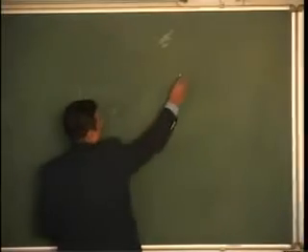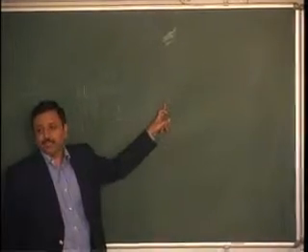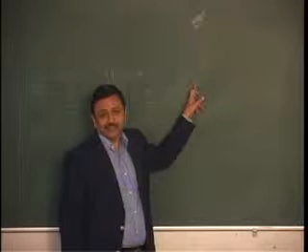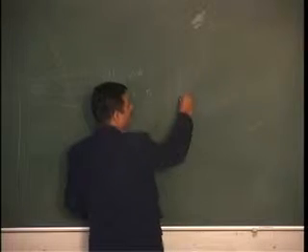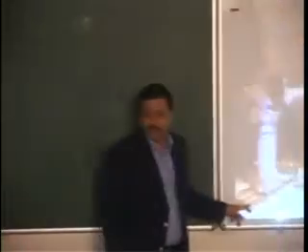There is one slide. The whole positioner is put on a slide, because even when we are talking about 40 dB or 30 dB errors, we are talking about error signals in the space. When the antenna is kept on a positioner, there may be a direct signal, and there may be one 40 dB down error signal. But this may also cause some error in the side lobe when we are predicting. So if I change the position of my antenna by moving it on the slide,